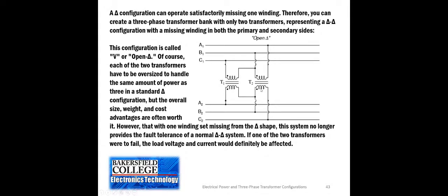Now, if you lose one of these transformers, then you're not going to have correct voltage across the lines because you only have single phase, and that's going to be a problem. So if one of the two transformers were to fail, then you would have a big issue. Now, there is a mathematical calculation to determine what the phase voltage is and the line voltage is. And interestingly enough, it's the same.